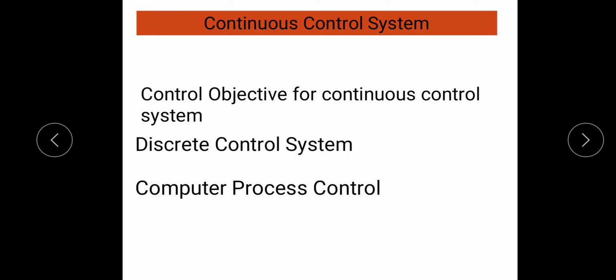The fourth objective is adaptive control, to overcome the disturbances to which steady state optimization is prone. Adaptive control uses feedback control and optimization by combining both practices. The feedback is provided in the usual external manner by the system, but the results are then utilized by a control algorithm that attempts to optimize an index of performance. As in steady state optimization, the system is thus adaptive and can cope with a time varying environment, as its internal parameters and mechanisms are not fixed.